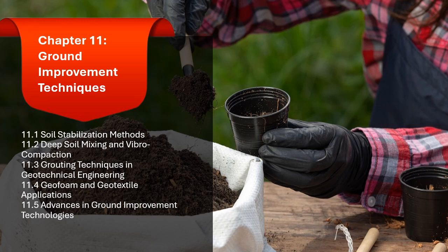Chapter 11. Ground Improvement Techniques. 11.3 Grouting Techniques in Geotechnical Engineering. Grouting is a ground improvement technique that involves injecting a fluid or semi-fluid material, called grout, into soil or rock formations to enhance their properties. The injected grout fills voids, cracks, and fractures in the soil or rock, improving their strength, stability, permeability, and other geotechnical characteristics.